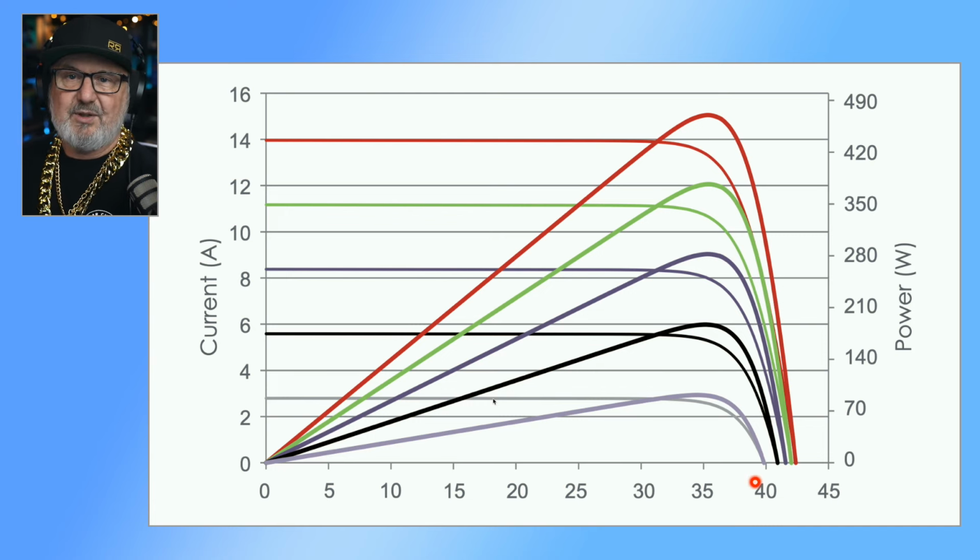It starts at open circuit, so first thing in the morning, the sun comes up, a peak voltage appears on the panels, but no current is flowing. So the inverter's just waiting for the voltage to get to its switch on point, which typically, for a single phase inverter, is 100 and something volts, and then it'll switch on, it'll start to draw current. So the inverter is a smart load. It's actually drawing a small amount of current to test if there is really any energy out there in the sun, and if there is, it keeps drawing current.